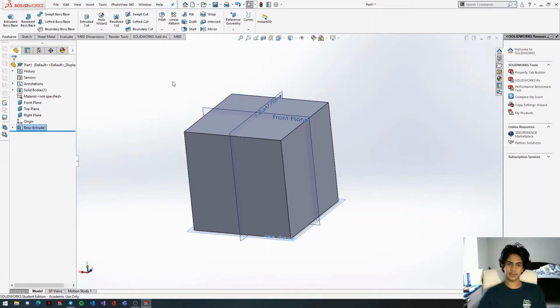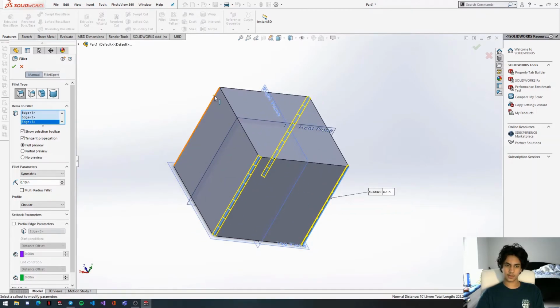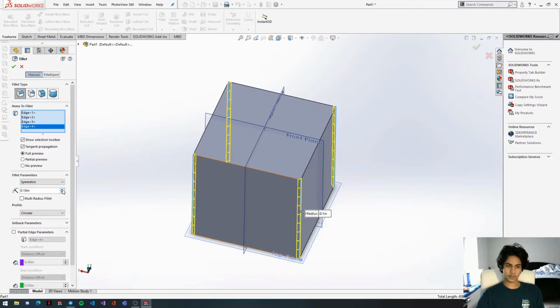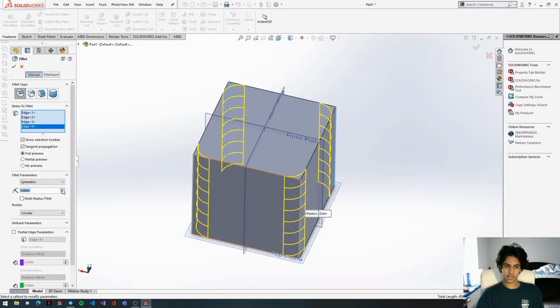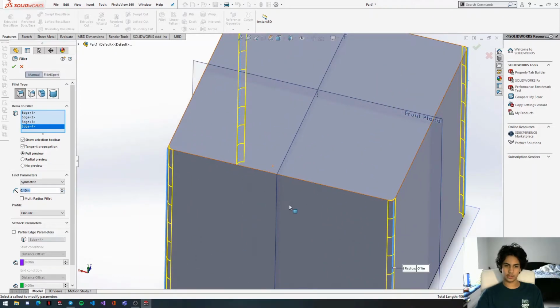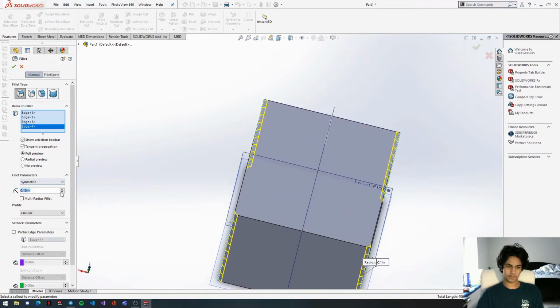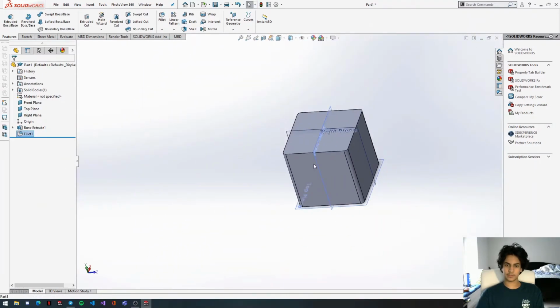So now we're going to do some aesthetic stuff. We have something up here called fillet. What fillet does is it takes a sharp edge and makes it rounded. So if we select all 4 of these edges, as you can see in this preview, it rounds out this edge. And over here, we can set the radius, or the severity of how much you're rounding the edge. If I go more up, it'll be a lot more severe of a fillet. And if we go more down, it'll get closer to that perfectly sharp edge. But we're going to set it at 0.2. Oh, oops, 0.2, and we're going to click check, and there we have some rounded edges.